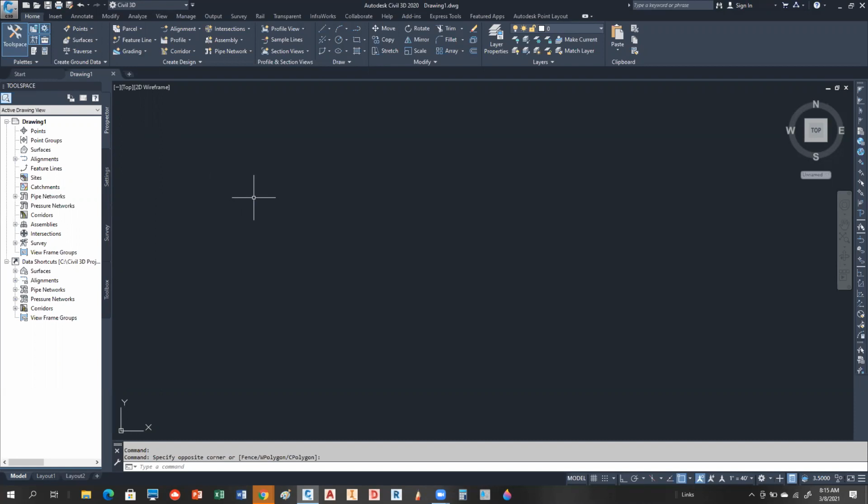Now the transparent tools are these over here. This tool is really important when you get into Civil 3D, so you don't ever want to lose it, so leave it there. There are ways of establishing things. That's an angle distance command. You have bearing distance, but we have point commands right here, so you can do it by point number or by point name or by point itself by just selecting. You can think of these as O-snaps that are specific to Civil 3D objects. Unlike the O-snaps down here, which have endpoint and those kinds of things, these are like snaps for Civil 3D objects.